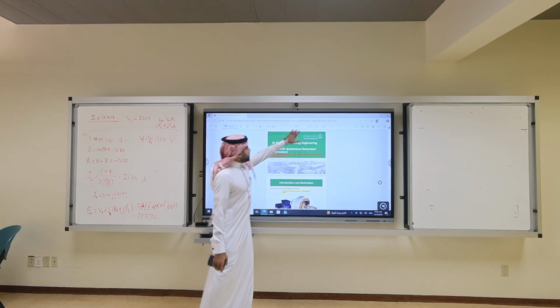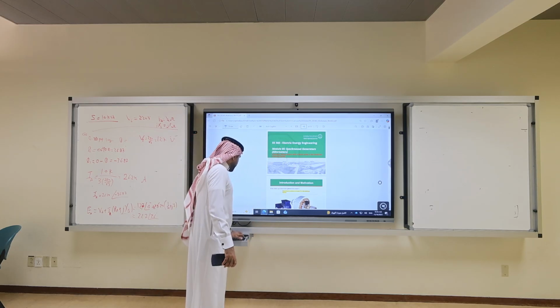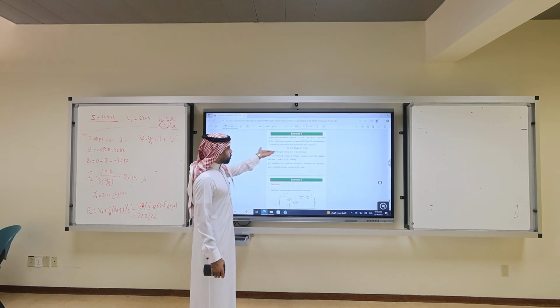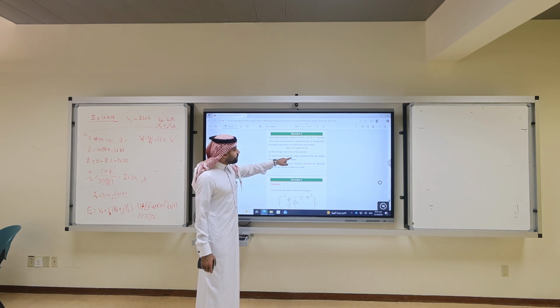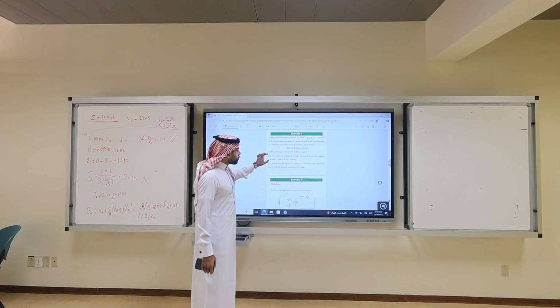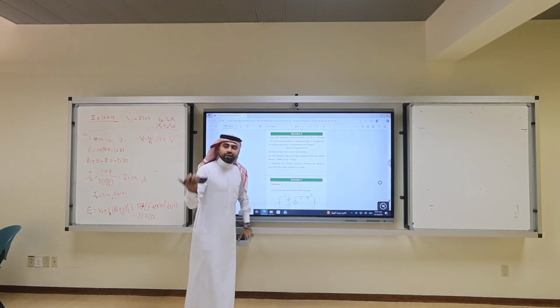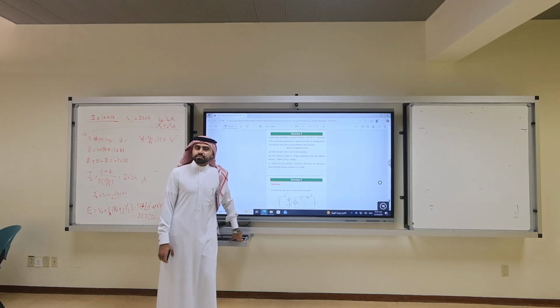Slide 7. Go back to slide 49. So, draw the equivalent circuit, easy. Find the induced voltage, VR, when the machine delivers 15 megawatt at 0.95 leading. In part B, are we operating at full load or not? How do I know? We multiply 20 by 0.9.